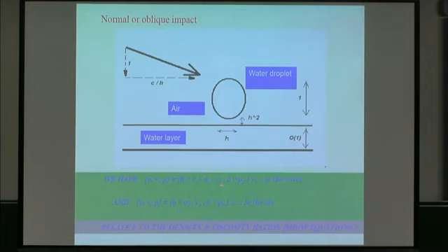That then can balance against the acceleration du/dt, dv/dt, which is of order 1 divided by the time scale, and the time scale is order h squared, so a small time scale because we're coming in at speed 1 and thinking about a distance of order h squared. So we sort of see the equations that are going to come out here, or that we're anticipating coming out.